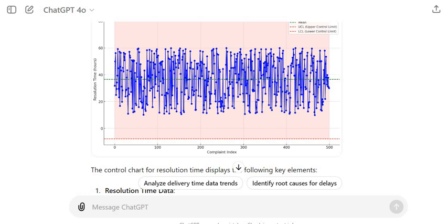But out of control means that there are not only natural variations, but some unnatural variations, in the sense that those are not the variations caused by nature, but these variations are being caused by some external factor or special cause, which needs to be identified and eliminated to bring the process in control.